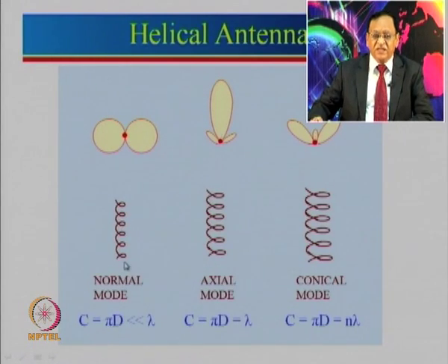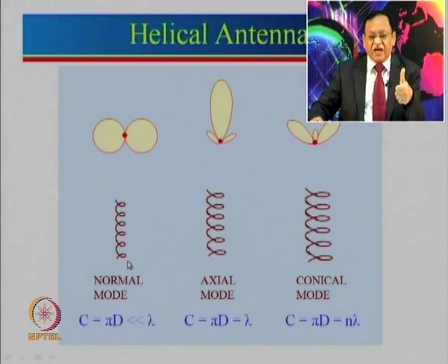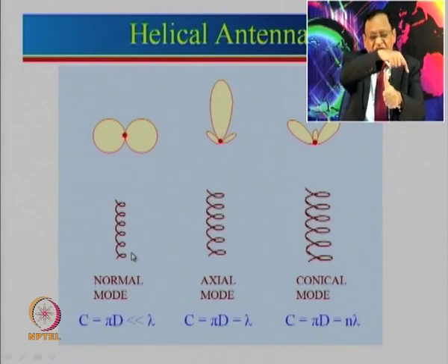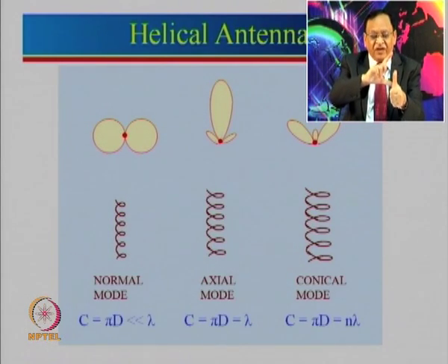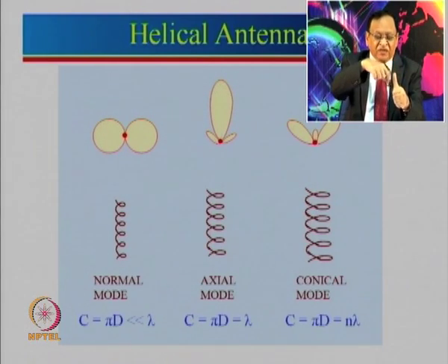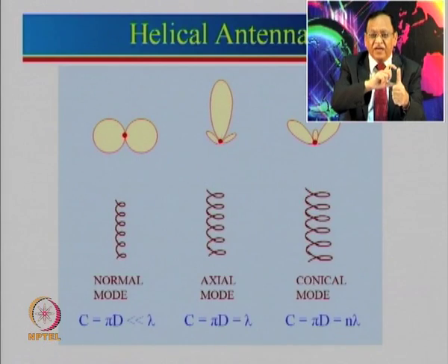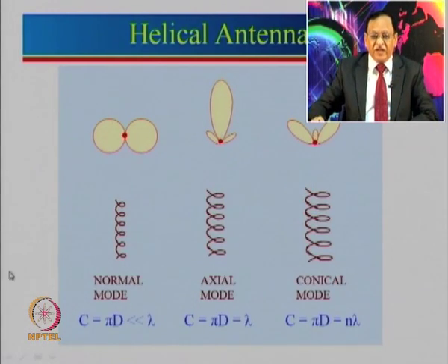This is very similar to a dipole antenna or a monopole antenna, where the radiation is maximum in this direction. So instead of having a large monopole antenna, that large monopole antenna is made compact, and the height is reduced. In fact, I did mention to you, for let us say a mobile phone at 900 megahertz, we would have a wavelength of 33 centimeter.